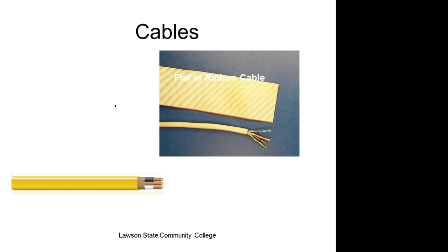And what's nice about those GFCIs, so y'all know the way houses are wired. What we do is we have a panel box. And then coming out of the panel box, we have one wire and then we have a circuit breaker. And then we come over here and then we have our plugs. Now you would think the plugs are wired in parallel, but really they're not. Normally what people do is it's got 2 screws on the side. And what I would do is I would bring my hot into one screw.